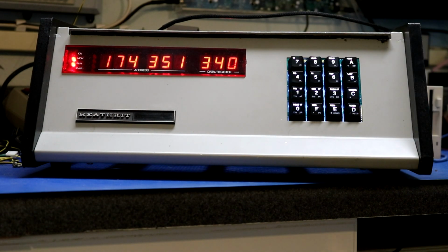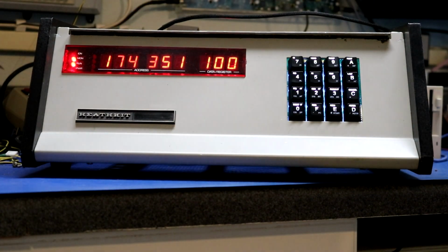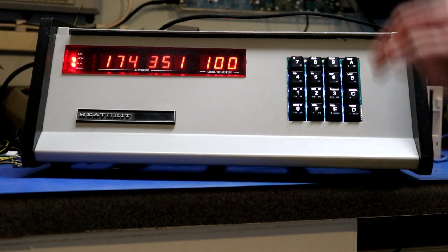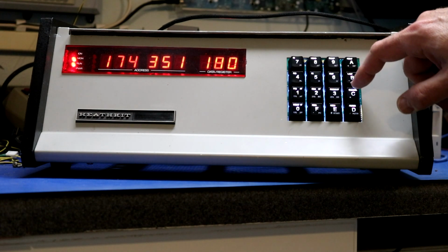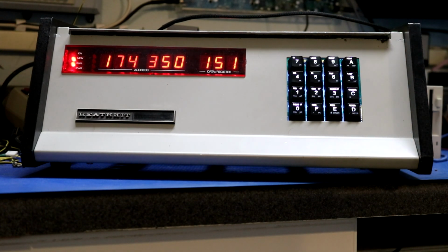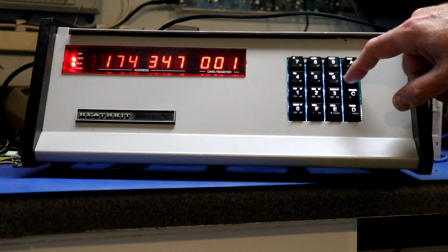So in the CPM kernel, I implemented a counter that is hooked up to the interrupt that is refreshing the displays. Every time it does a refresh, it increments this counter. This is at memory address 174.351 octal. So if we go up, this is the least significant bit. It's changing very often. Go up and look at another more significant byte. We can see it changes less often. It's actually 32 bits, so we can keep on going.